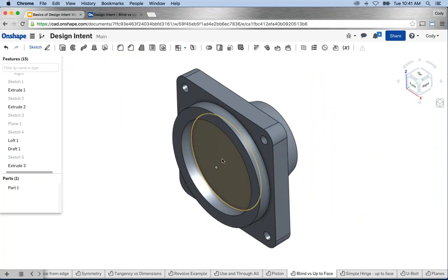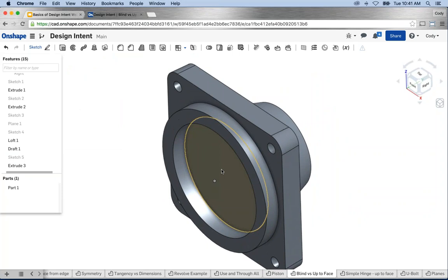And it's a very easy mistake to make. I'm just using a blind depth of a certain amount. And it may work at that moment, but when you change it, you'll find that it doesn't. Right, and you often have to go back and make another change to that depth. So again, a blind value or just entering a number is oftentimes, if you have an option to do something else, you're better off doing that. It allows you to better reflect your design intent.